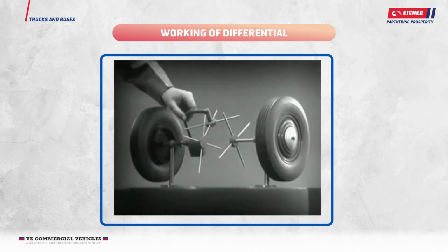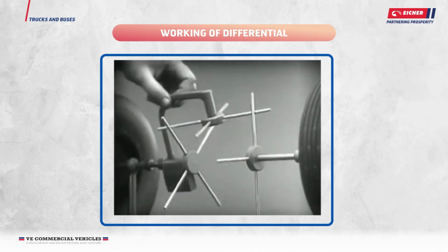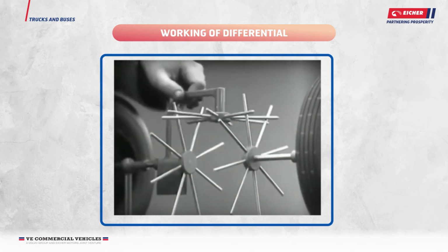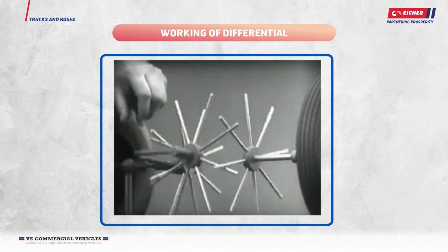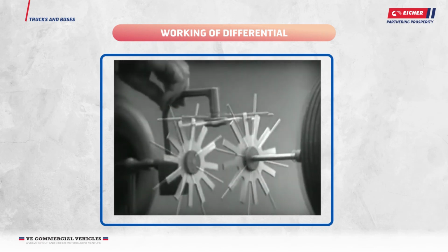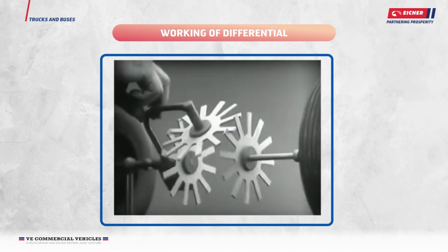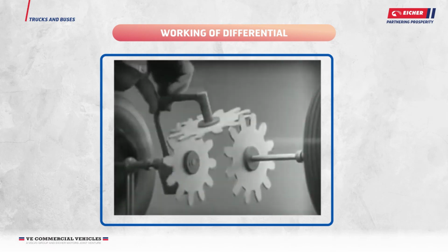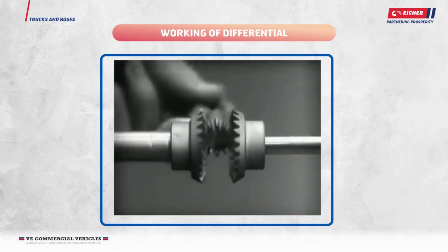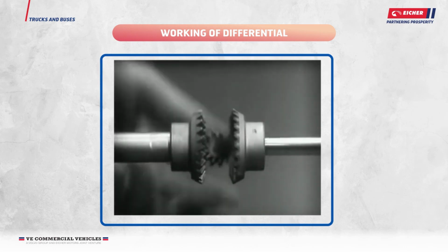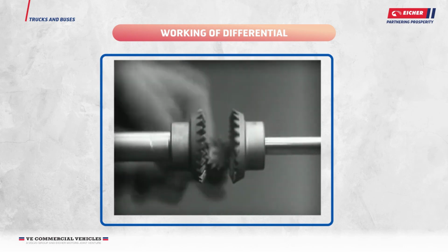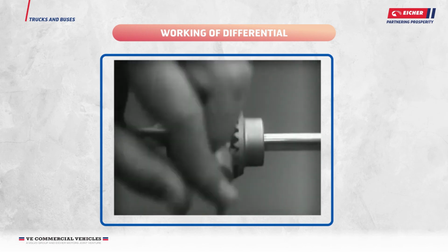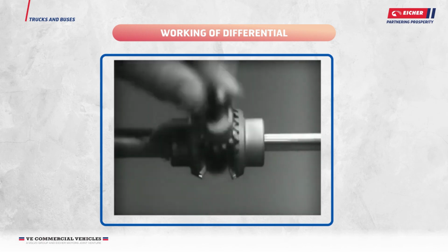In order to reduce the jerky action caused by wide spaces between the spokes, we will put in more spokes. Further filling in the spaces between the spokes gives steadier, more continuous action, and changing the shape gives firm, constant contact. Now we can make the gears thicker and stronger, and we have differential gears. The edges are cut so that they will fit together more smoothly and silently, and another gear is added to share the work of driving the axles. The principle is the same.